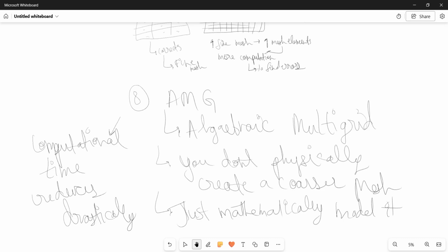So you are now algebraically trying to form the meshes, the coarser ones, multigrid coarser meshes. Then you're calculating error as you were doing the multigrid system. Then correct those errors. Then convert it back to the finer mesh. It was already a finer mesh. The mesh geometrically remained fine itself, but mathematically you converted it into your coarser mesh and found the errors through those mathematical equations, and then you distributed all the corrections and just kicked them back into the finer one. But geometrically the whole surface still had the finer mesh, right?